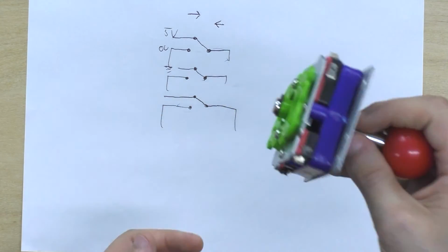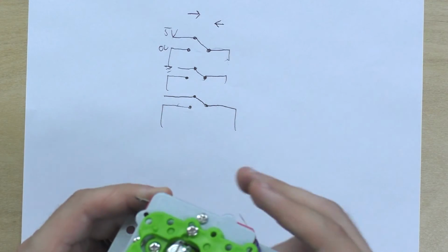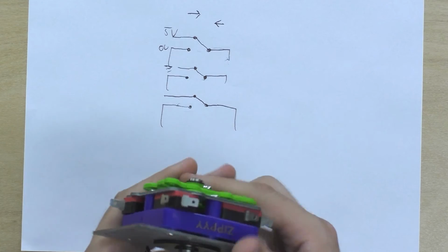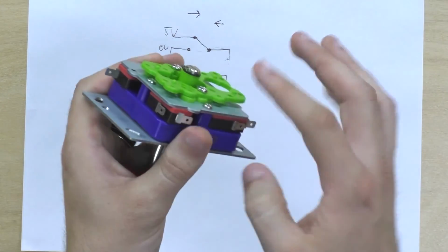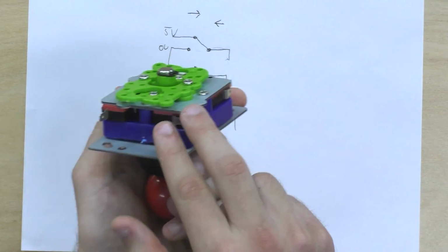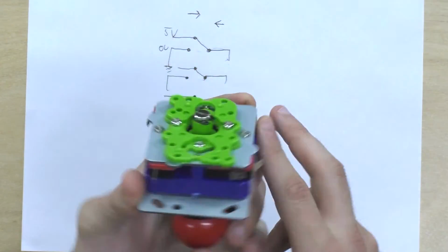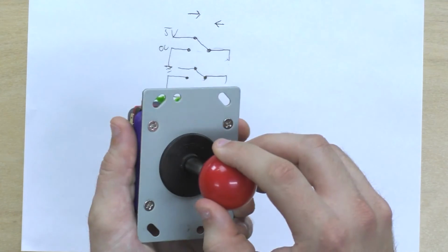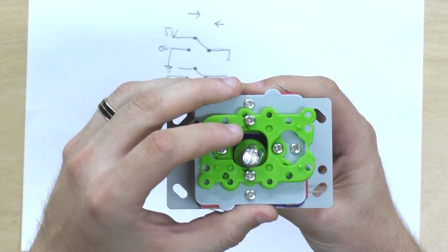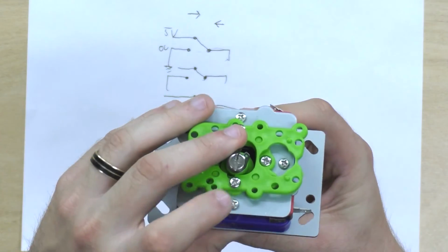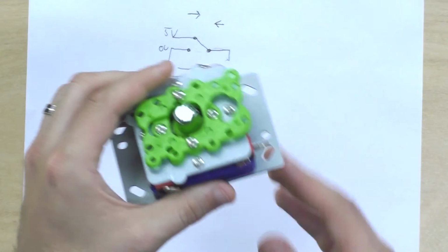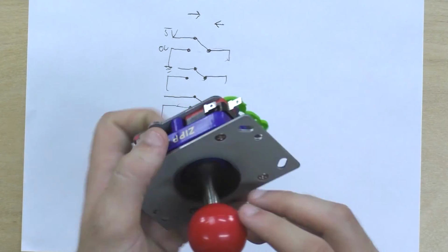Now it's actually incredibly simple. You have 4 sets of switches here, and these are single pole, single throw switches. They're make or break switches. You can see here there's 2 contacts there, 2 contacts there, 2 contacts there, and 2 contacts there. Now this joystick simply makes a connection. So you can see the other arm of the joystick here. It's making a switch connection here, and there, and there, and there. So it really just makes a switch in either direction.